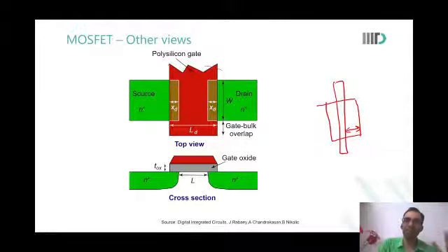Yes, sir. Then you're automatically giving away the control that you would have had to the tool. You make the layout by hand. Make the active region, make the poly. You will have all the control. So right now, when we have done the schematic, then we do generate from source and we get PMOS and NMOS. Don't do that. So don't do that.